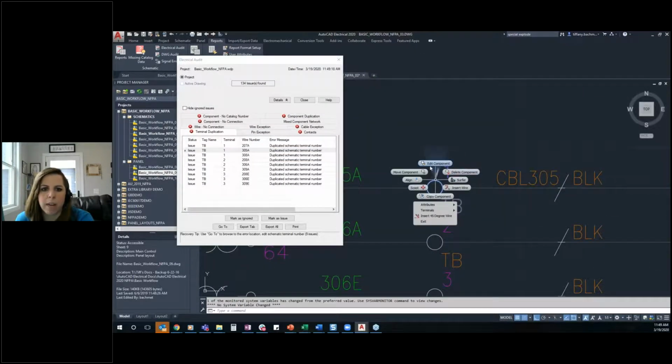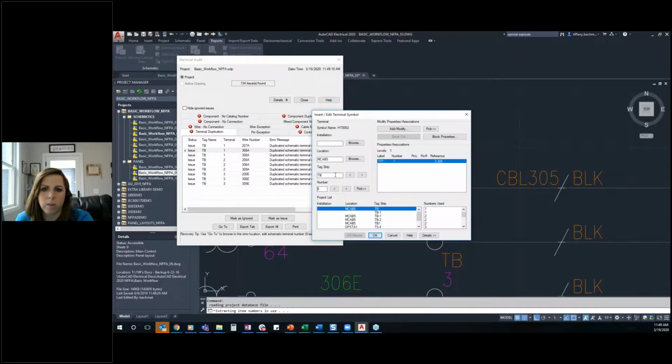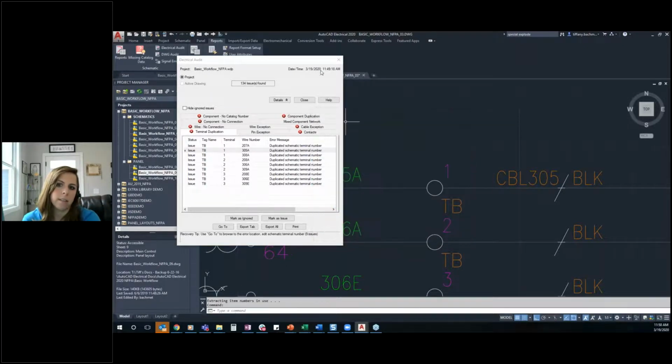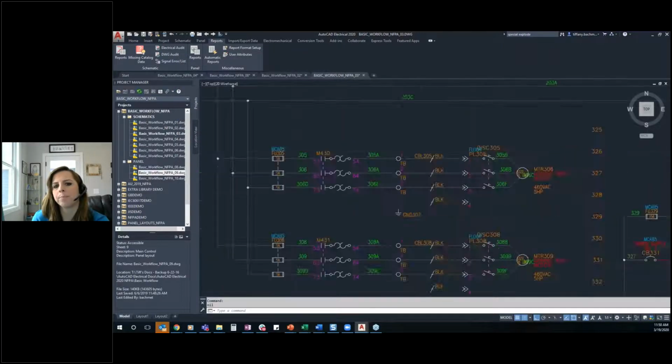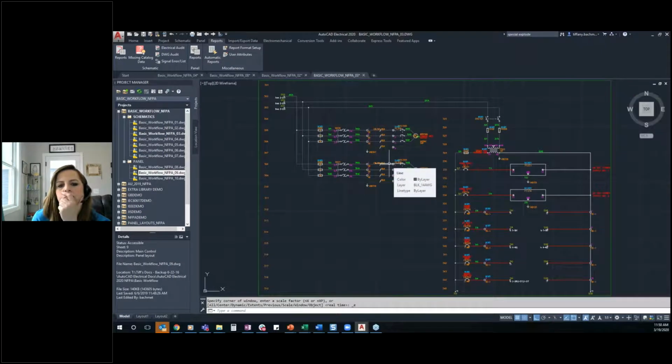And I should be able to go in and edit that as needed, to switch out what the tag strip is or change the terminal number or increase it. Now, if you use our copy tools within it, like if you're copying it because you need it to be a part of the same terminal strip but increase numbers, we have options for that. When you copy the circuit, you can say, I want these terminal numbers to increase. Yeah, so this is in the X data though. There's some unique identification in every terminal that associates it with, I guess, a footprint.